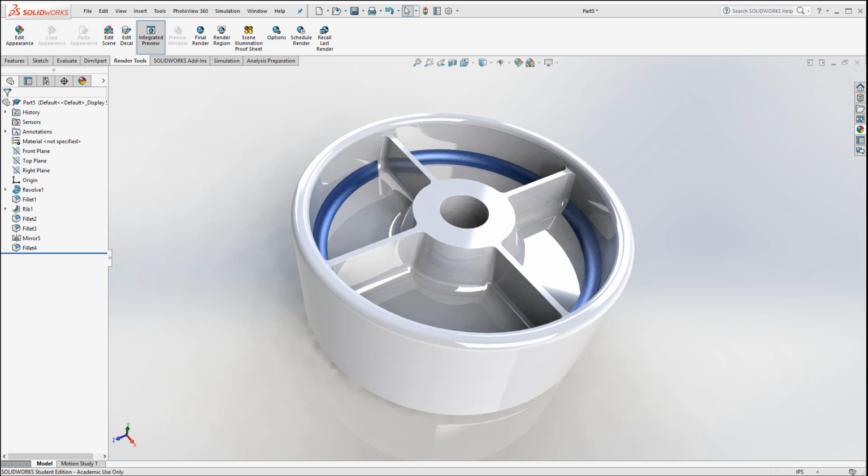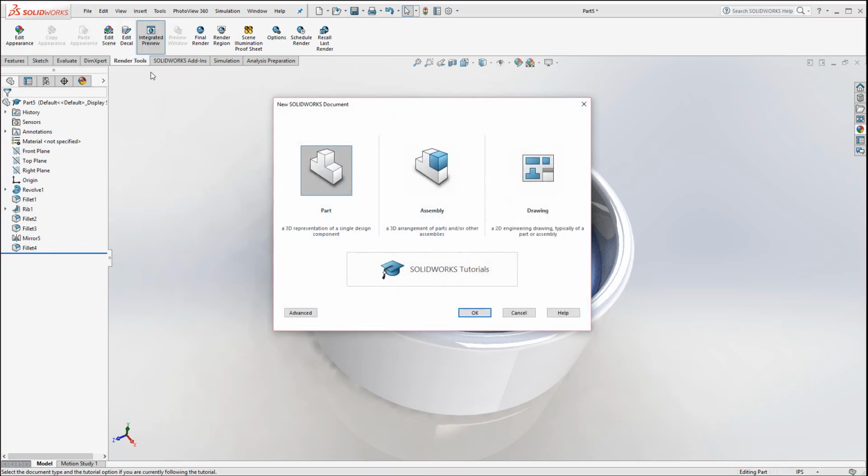Exercise 2, SolidWorks 2016. This exercise has to do with Revolve features. We're also going to take a look at the rib feature, some sketching techniques and dimensioning, like dimensioning angles, and a little bit more mirroring, and how to build a part like what you see up there. So let's begin. Start with a new part file.